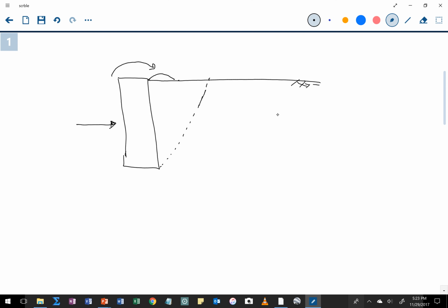And what we have happening is that the soil is trying to move that way, and we have friction along that failure plane going that way. You see how the two arrows are moving basically against one another, towards each other. So this is compression in the soil. When we have that type of compression, we call this, again, the passive condition or the passive loading case.